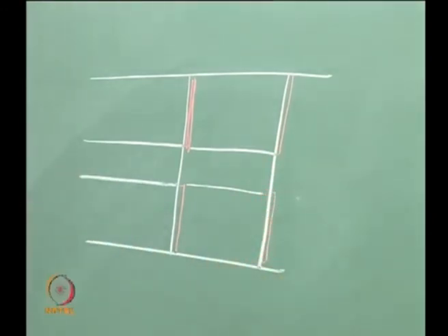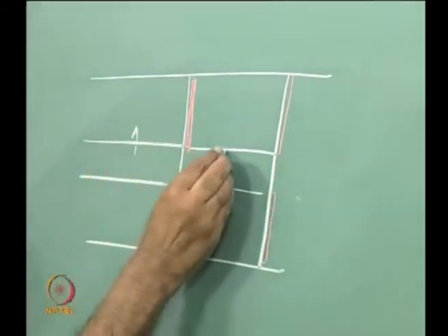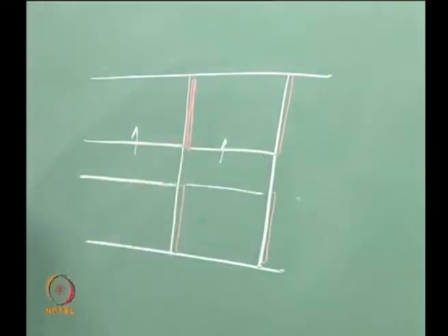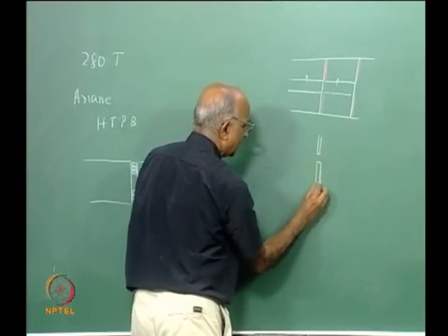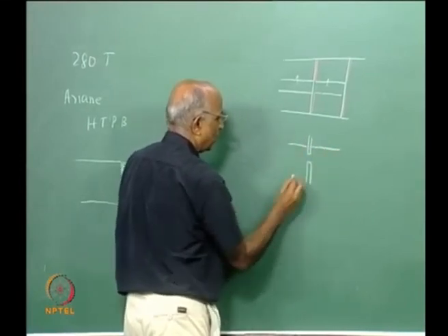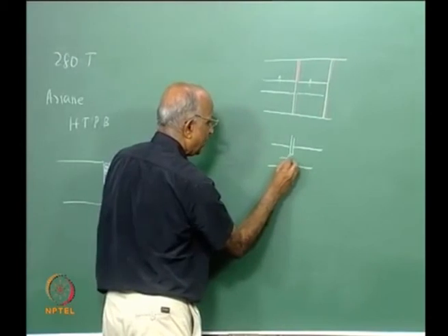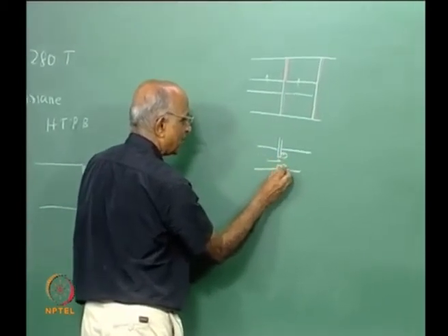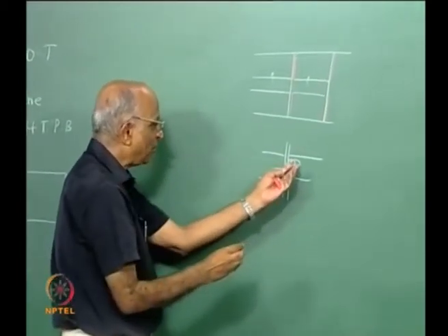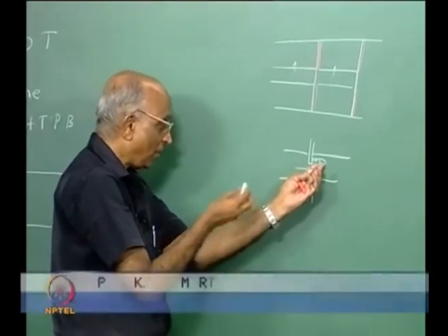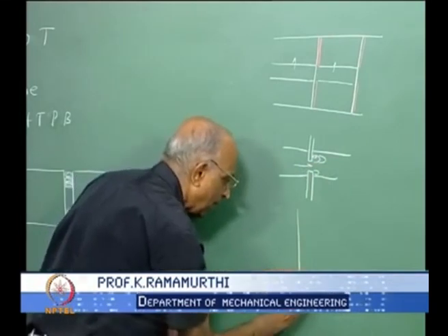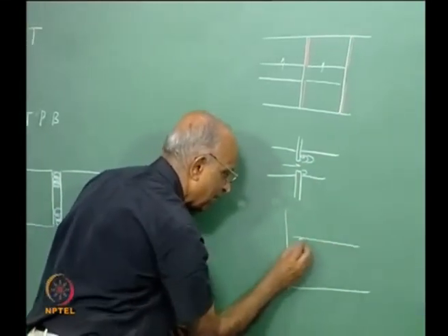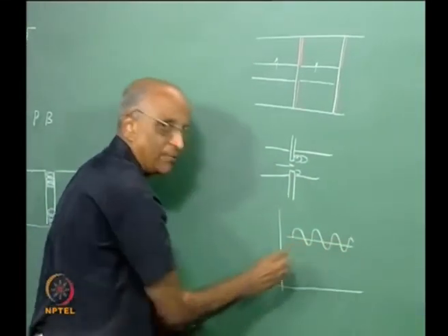Now when the propellant burns fast, whereas this fellow does not burn fast, therefore after some time I have the inhibitors standing like this, the propellant is over here, the flow takes place here, and therefore some eddies are formed. These eddies in the flow have a characteristic frequency of disturbances, and these disturbances get amplified, and the thrust, instead of being steady, starts oscillating.